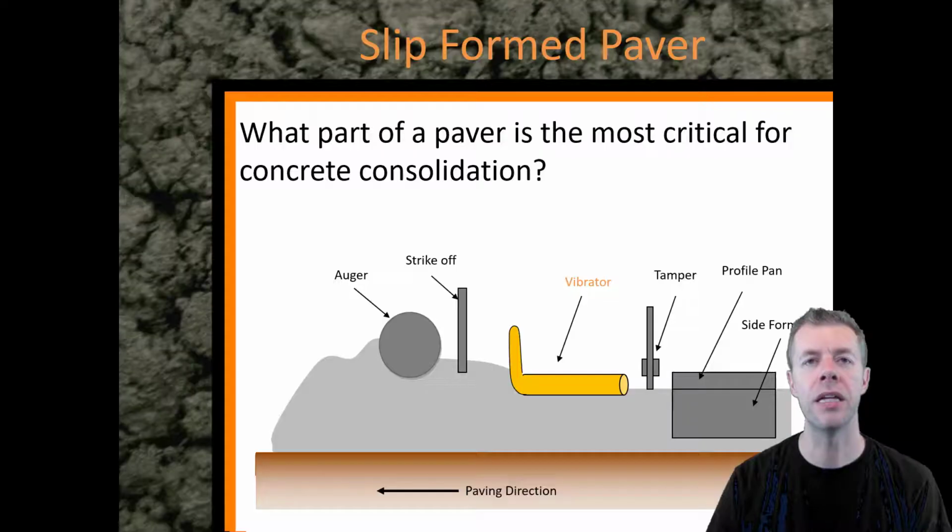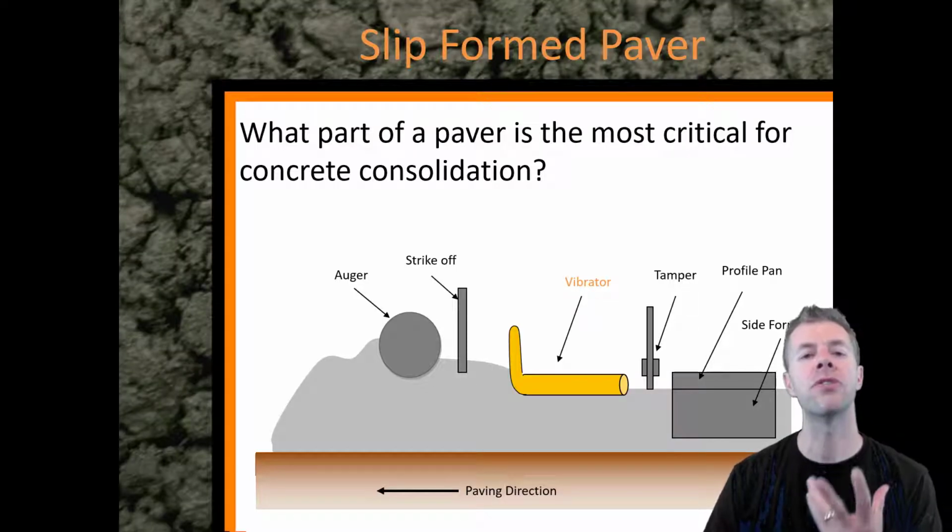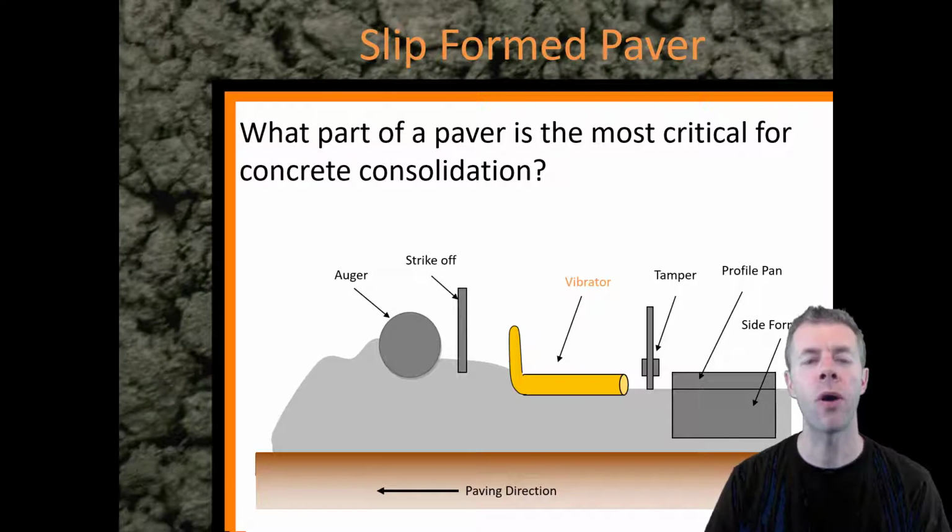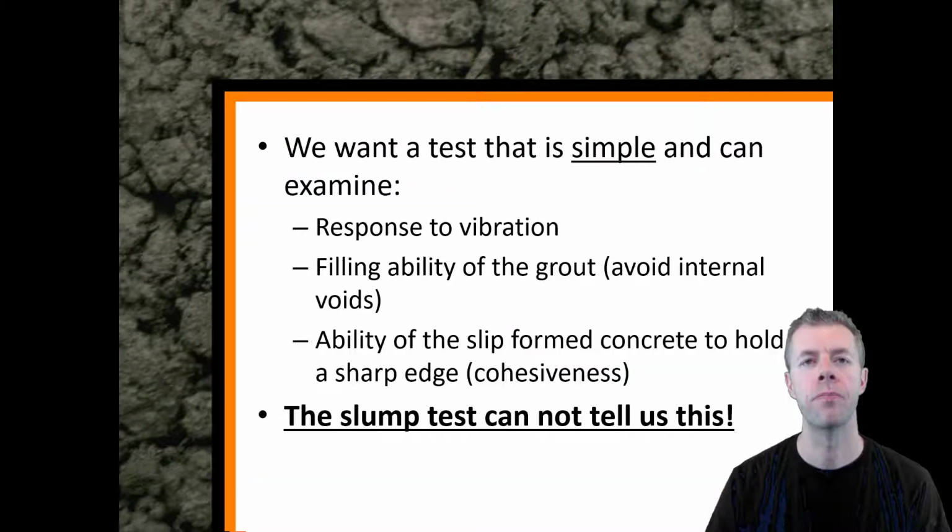And to investigate it, we had to understand and think about, how does a paver work? We had to realize that the part of the paver that does the most effort of consolidation is the vibrator. So we needed to understand, how does the concrete respond to vibration? And then how does it hold an edge after you're done vibrating it?